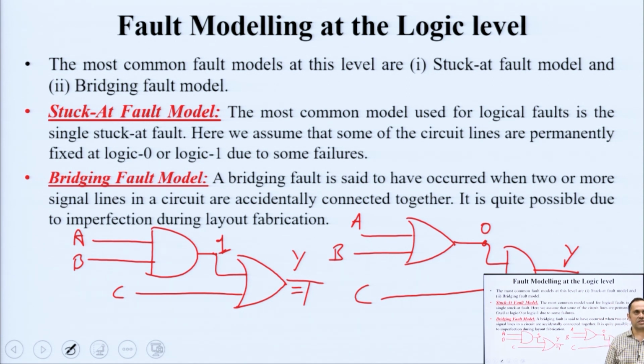So, I would say that this circuit has a fault which is known as stuck at 0 fault. To identify a stuck at 1 fault, suppose I apply 0 here, I apply 1 here and apply a 0 here. Logically, I should get 0 here, I should get 0 here and output as 0. But if I get an output 1 here, it means the problem lies here.